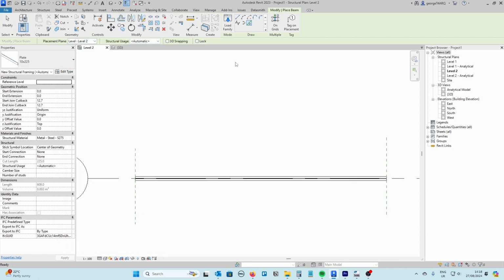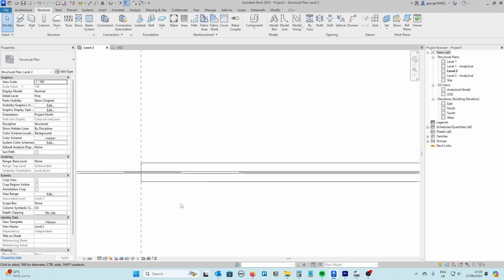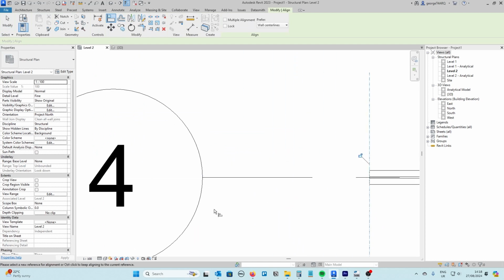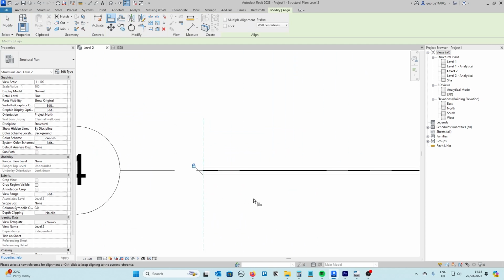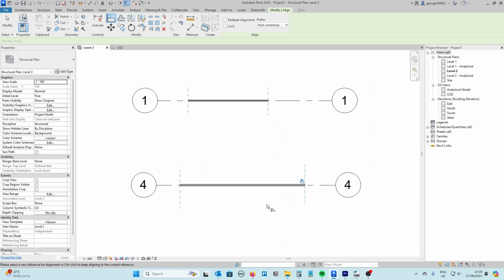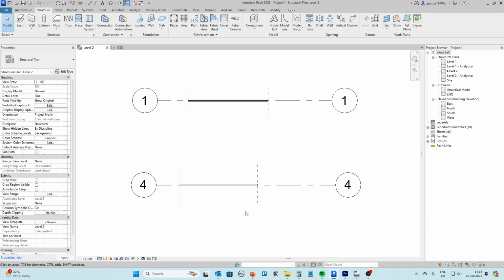Okay, and we will put this straight down the middle, and again, AL, lock it to this reference plane. So always get the padlock and constrain it, like so. And now what you'll see is this length we can then change, and that's taken all those members together.